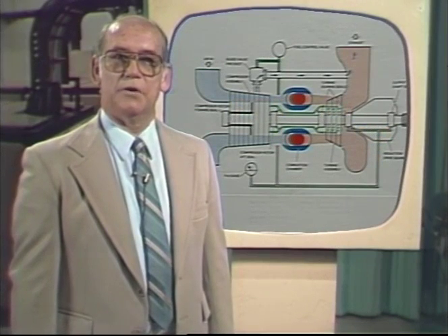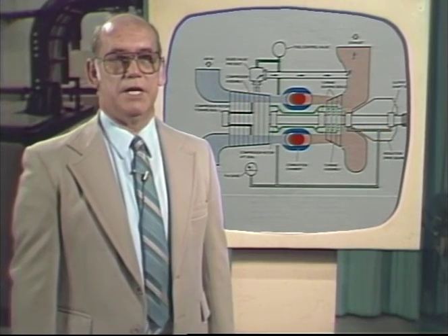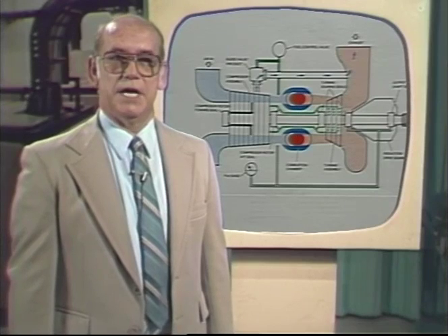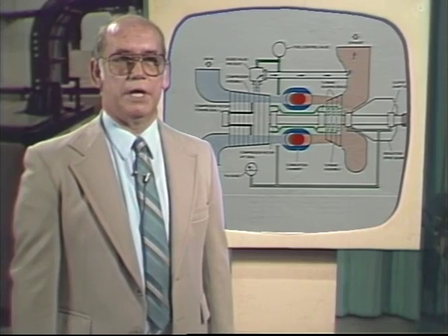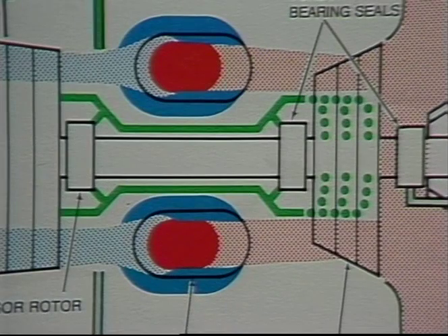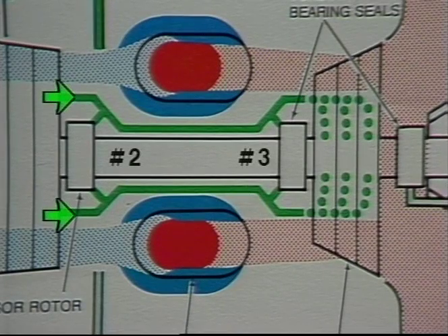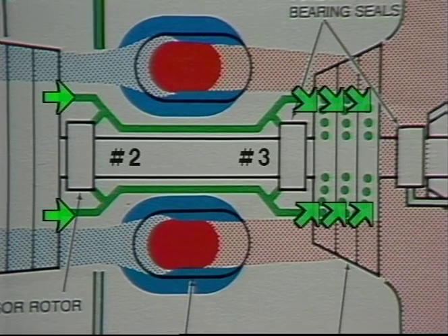Back pressure could result if improperly sized vent lines are used. A test of back pressure should indicate no more than 1-inch water gauge. In addition to pressurizing the number 2 and 3 oil seals, 8th stage compressor air is used to cool the turbine rotor disc.